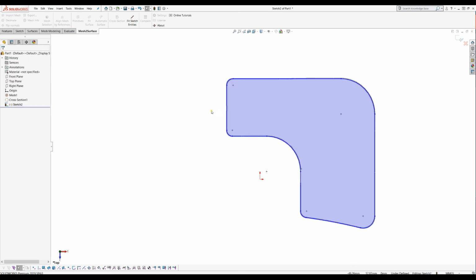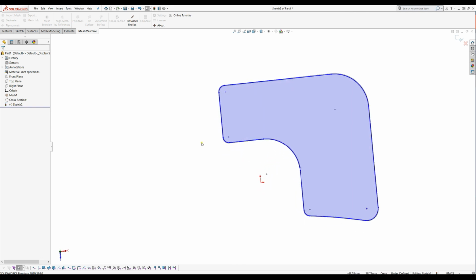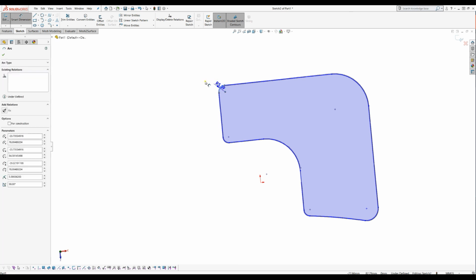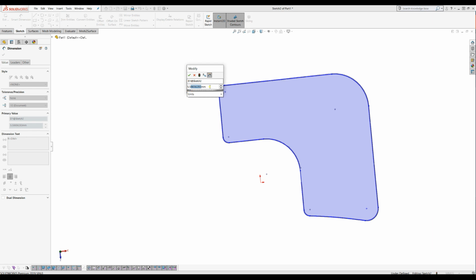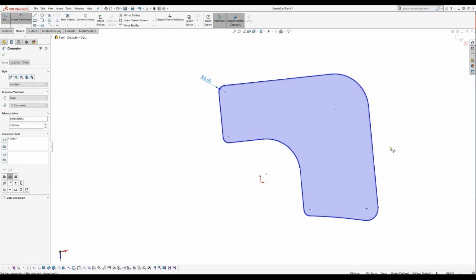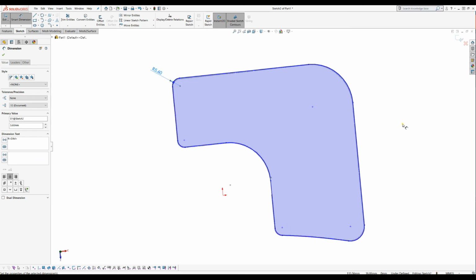It takes a while until it generates the sketch in SolidWorks. As you can see, this is just a default standard sketch, which you can now use to define your smart dimensions. As you see here, it's 559, and you can just make it 560. Why I show this is that these are just standard features of SolidWorks, and you can finish off your work here. I hope this is useful. Thank you for watching.